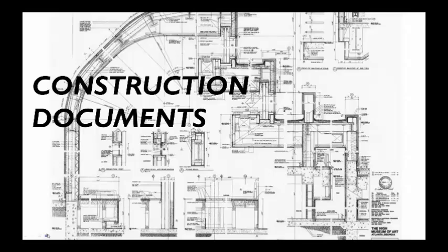And so that's when we start looking at all these cutaway sections of walls and different details and connections in the building, showing all of the dimensions, showing all of the materials, all the places where you have framing and insulation and glass, and exactly how far everything is spaced apart, and not just in one certain area of the building, but everywhere.